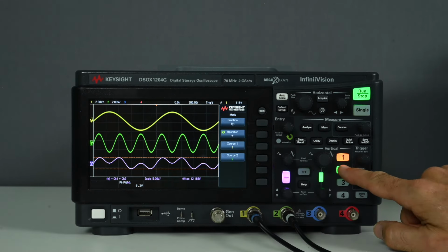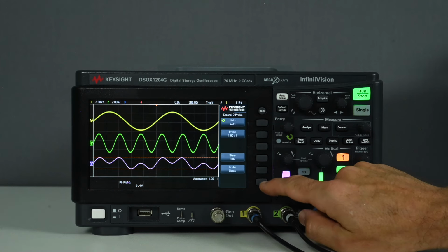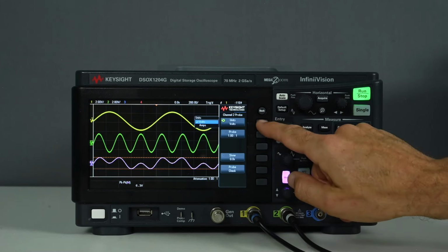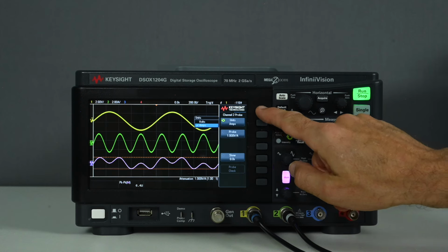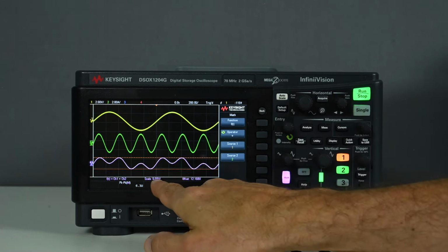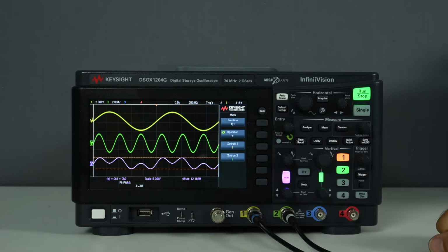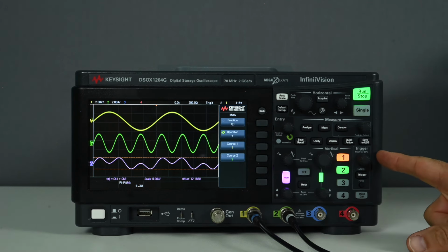But now suppose that I'm adding volts to current. So I'm going to put the second channel here on current. I go back to the math function, and it shows me the scale is 5U, where U stands for undefined unit because I'm making a strange combination. The Siglent also does that, I think.